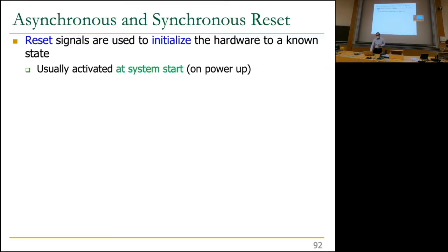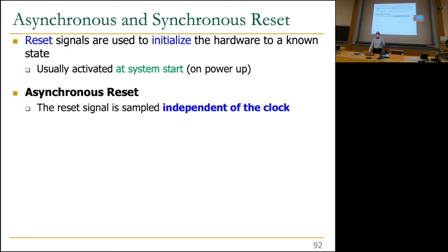Okay, so I kind of said this. For this, you need a reset signal. Right? Usually, this reset signal is activated at system start on power up, but there could be other cases also potentially. And there are two ways of designing the reset signal. One is asynchronous to the clock, and the second is synchronous to the clock. This is very similar to synchronous versus asynchronous design principles that we discussed earlier. So asynchronous says reset happens whenever it happens. It's independent of the clock, basically.